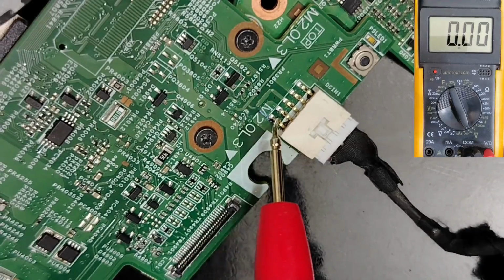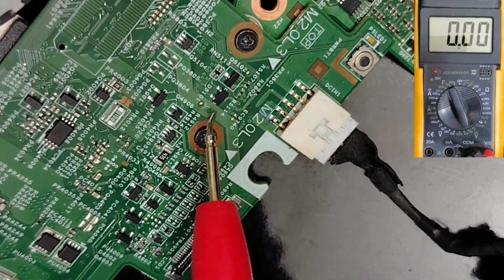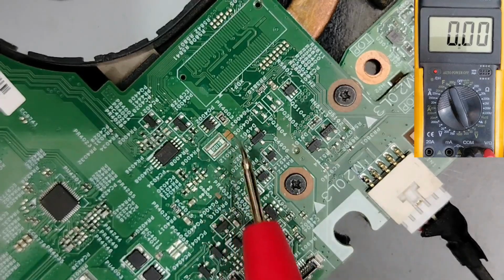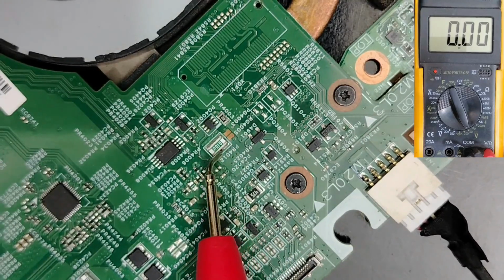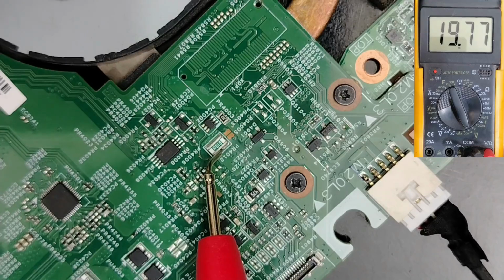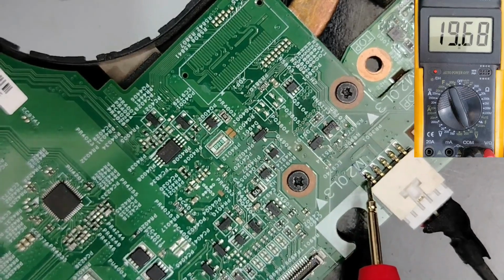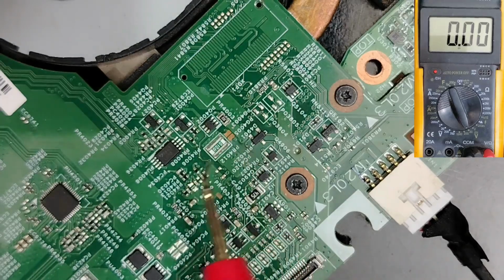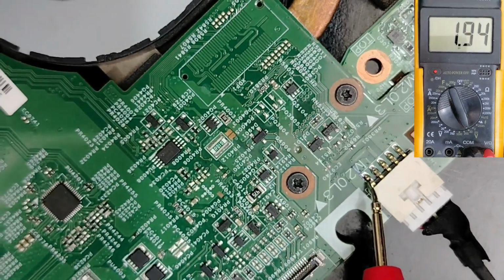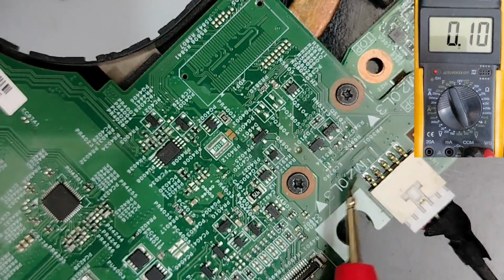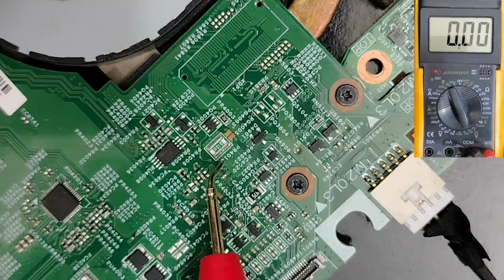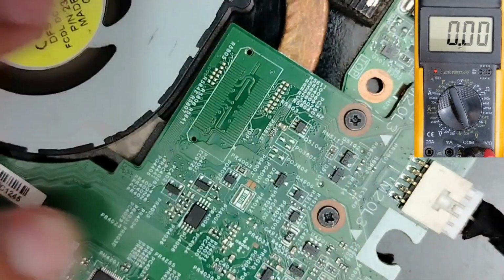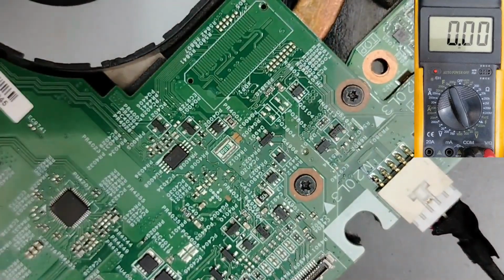So how can we check if the 19 volt passes to the motherboard or not? By looking at inductors or a current sense resistor, like this one, for example. If we check it, we have 19 volt. Do you see, guys? The main 19 volt passes from the power jack to the motherboard, because here we have 19 volt. But in some motherboards you can't find 19 volt here, because we have a dry joint, so you will not find 19 volt at the current sense resistor, which means the B plus voltage is not distributed in the board.